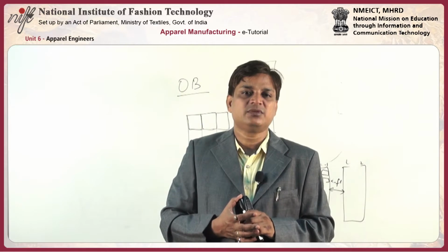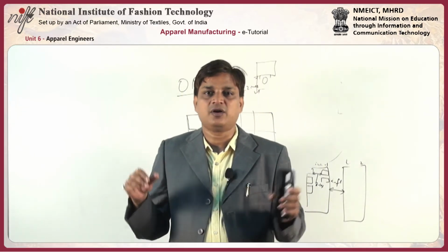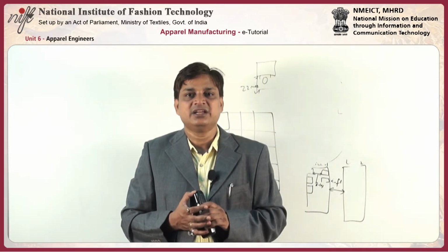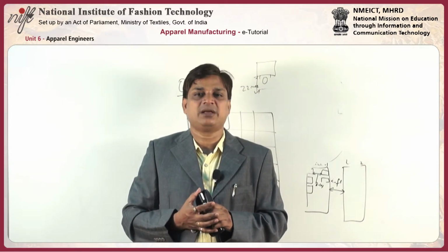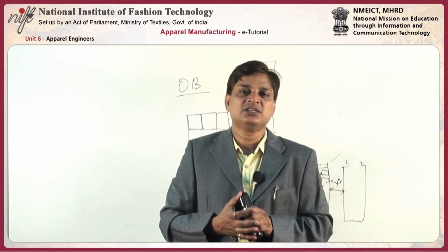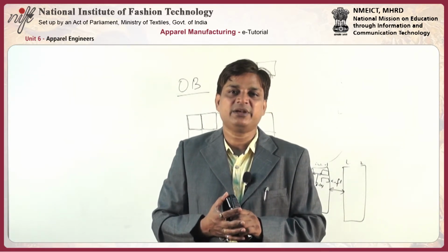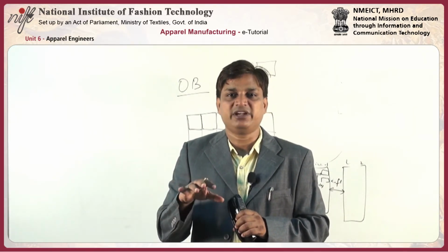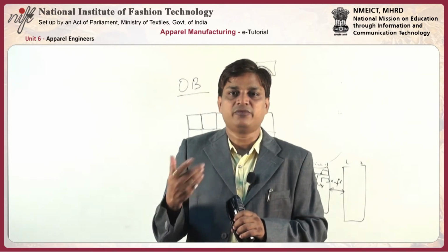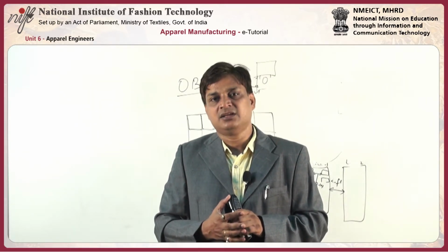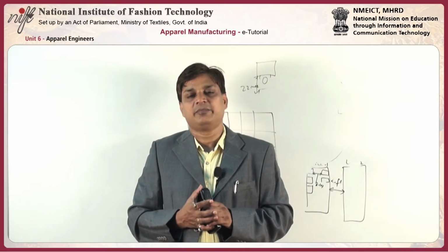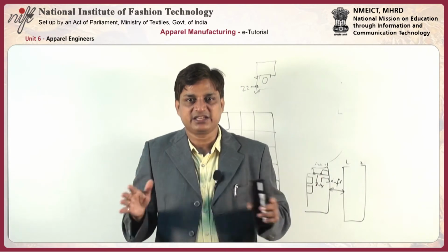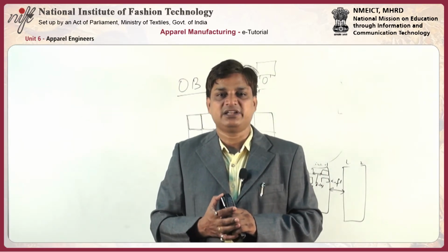Then the maintenance room. How big we want to make the maintenance room depends on the number of machines we have in the factory, how much preventive maintenance we are going to do, how many machines will go for preventive maintenance per day, how we are going to do it, and how many machines we expect to have breakdowns. All these things have to be taken care of when deciding on the maintenance room.